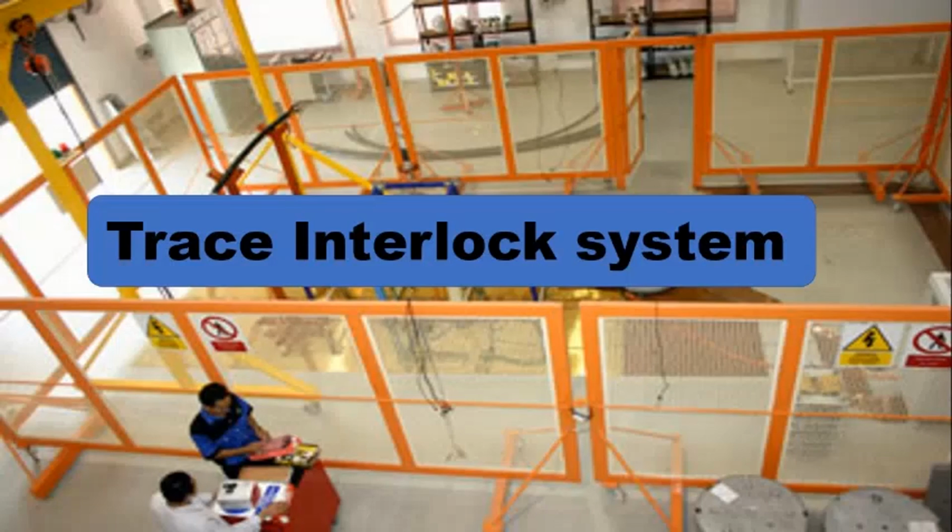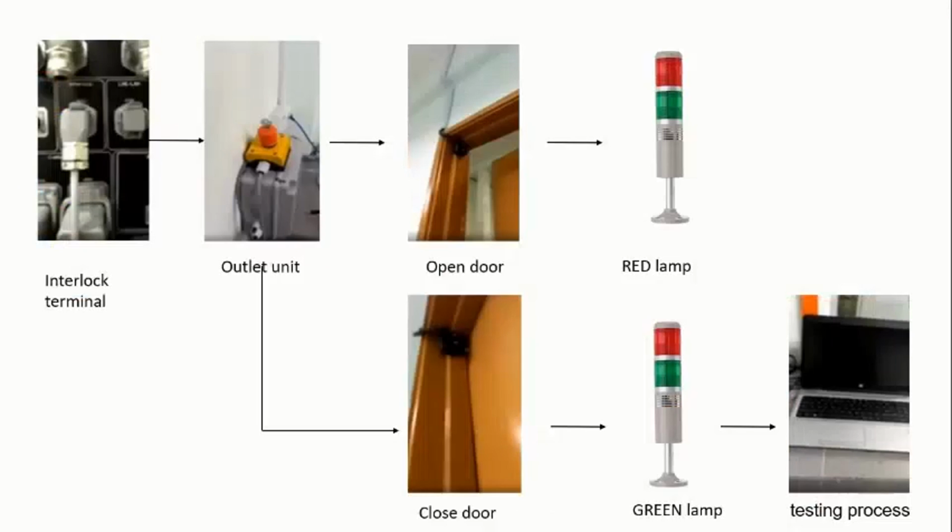Interlock is used to monitor the door to the high voltage part of the system and to monitor if the ground rod is taken out from the high voltage. It can also be a door in a safety fence mounted around the HV part. During the testing process, if the door is open, the injection or testing process will not be possible because the red alarm will always be live in the system. And when the door is closed, the injection or testing process can proceed.